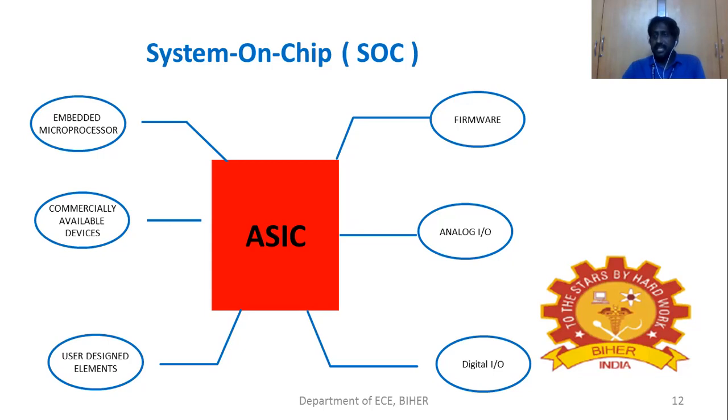Modern devices have inbuilt ADC and DAC themselves, because most real environment signals are analog signals. For example, our voice signal is an analog signal. Your microprocessor can process only a digital signal, so before processing we need to convert it into a digital signal with the help of ADC. The analog to digital converter can be used on chip or off chip. Modern devices allow an on-chip ADC as well as a DAC.